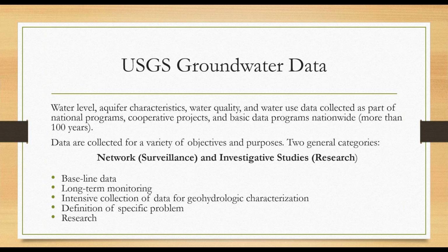Within those categories, there is baseline data. Baseline data, what we mean by that is we get information for determining the future changes from the initial or baseline conditions. The baseline data establishes a benchmark for future investigations. There's also long-term monitoring. Long-term monitoring looks at temporal trends or changes over time, and is often needed for calibration of groundwater models and things like that.